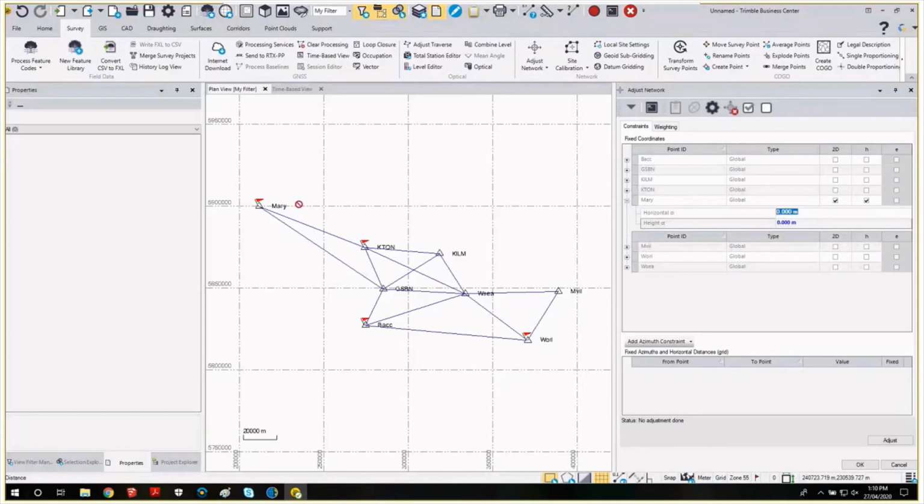But what we are going to do is enter what the state government says this particular coordinate is known to, its quality, so that our error ellipses reflect the same thing if we were to report back to the government that we've established a network with this coordinate at a 95% confidence interval.